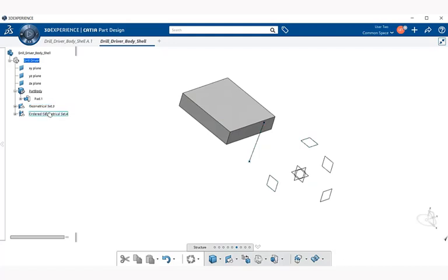Now that we have some already created, let's open up the geometrical set. Notice we have some items placed in here, and these are basically used as references at this point. A geometrical set can be used to house or contain, as we talked about earlier, reference entities such as lines, points, or planes. This way you can use the same ones over and over again without having them fall into a timestamp formation, like under the part body or even an ordered geometrical set.